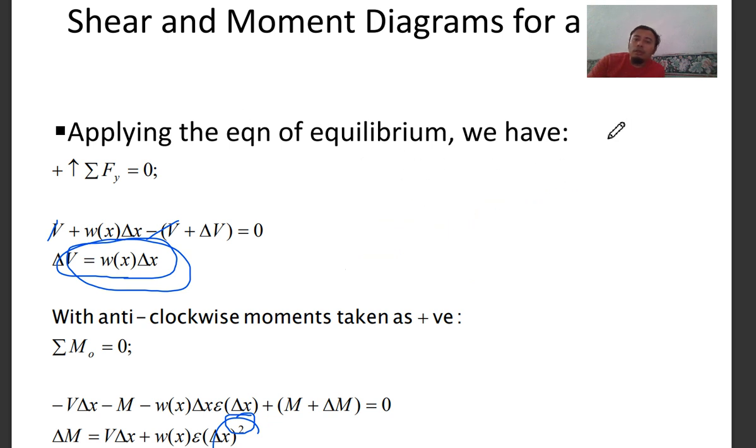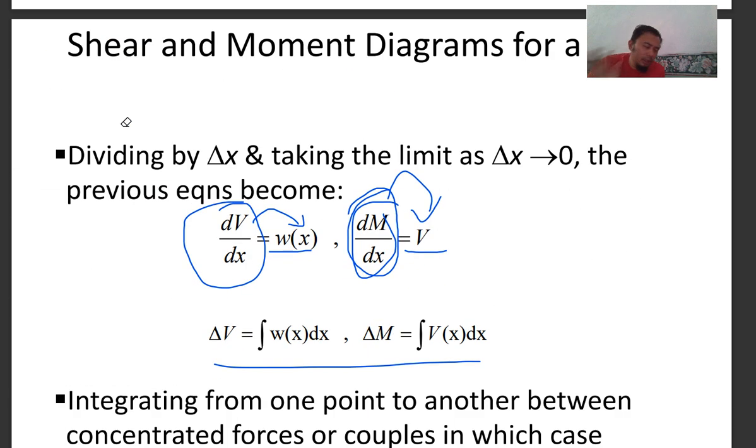When it's a point load, the load acts at one point. If it is a distributed load, the load is applied gradually, increasing up to a maximum point. If it is uniformly distributed or a triangular load, the rate of increase is different. The rate of increase affects your graph of the shear force diagram.